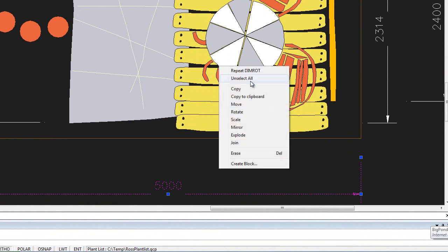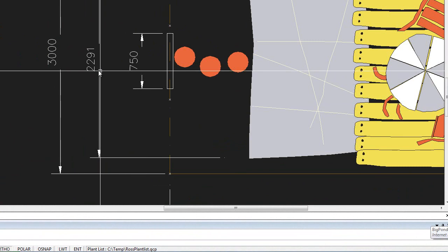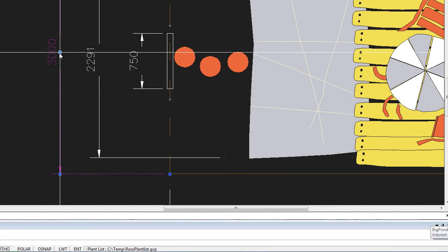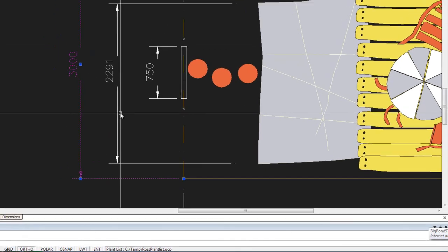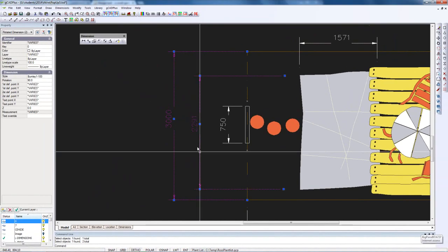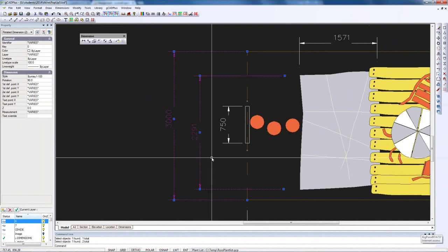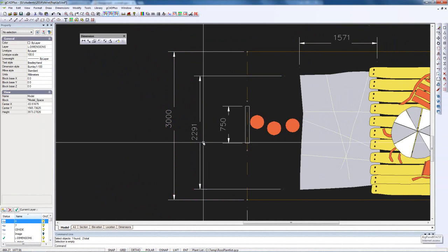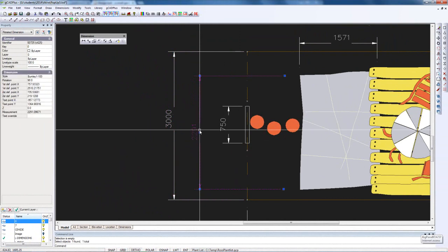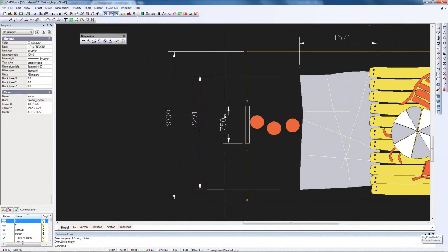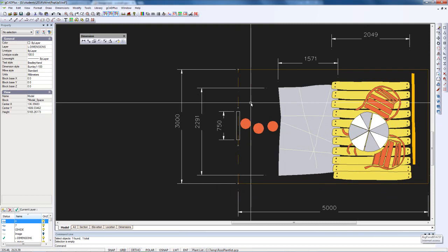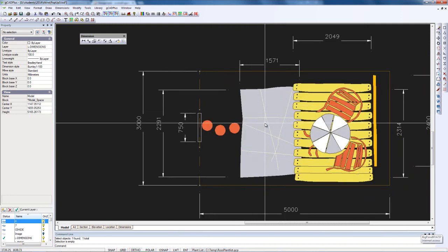and we'll unselect those. We could come over here and look at these dimensions, and they ought to be lined up a little better. That one's in about the midpoint of there. This one I think could come across here, and that one seems to be in the midpoint. Some people would prefer to line all the dimensions up in that way, although you clearly can't do it in this one. Try not to cross dimension lines and try not to cross important information.